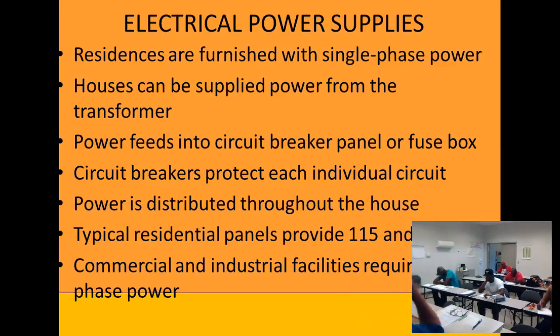Now, you may think, hey, heating up a wire is not very useful, but when you heat up a coil to heat your house, it is. Or if you heat up the filament in an incandescent light bulb, and it glows and gives you light. So those are called resistive loads. They use resistance to the flow of electrons, and they produce heat and light, or both. And then the third for our HVAC is capacitive loads.